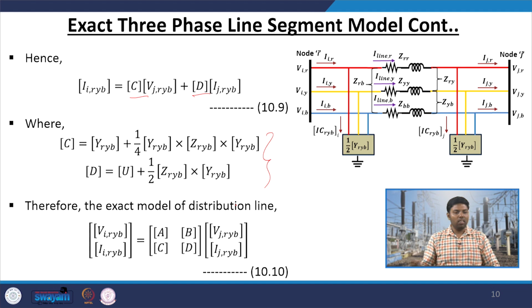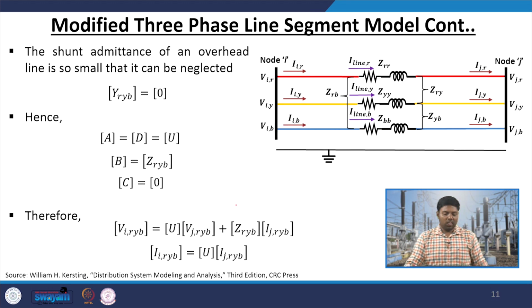So, we have represented our 3-phase unbalanced distribution network with its equivalent pi model corresponding to its ABCD parameters, which is the conventional transmission network model we have used for medium transmission line modeling, or maybe long line approximated pi model modeling, which is normally used for determining the sending and receiving end quantities depending upon the voltage and current values. So, generally in case of overhead lines, the capacitance value is less, that we know, and that is even true for transmission systems as well as distribution systems.